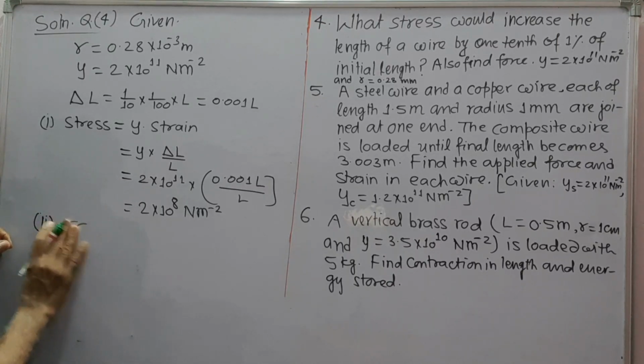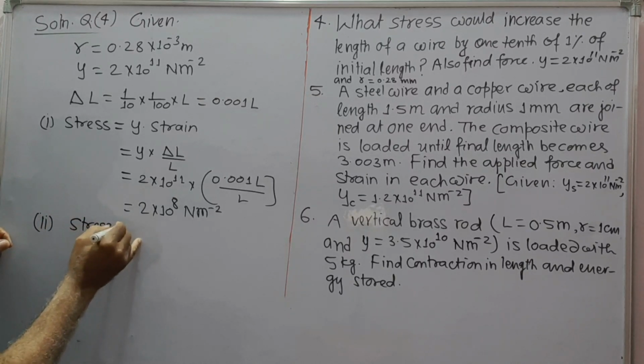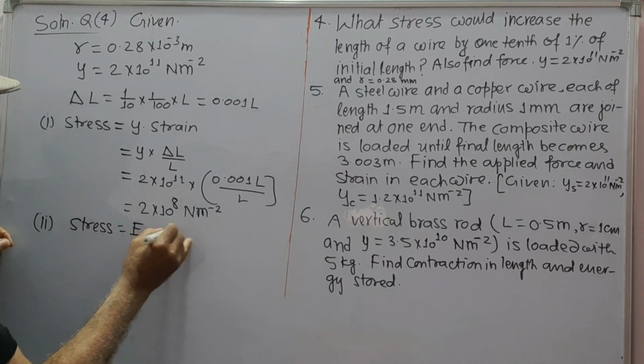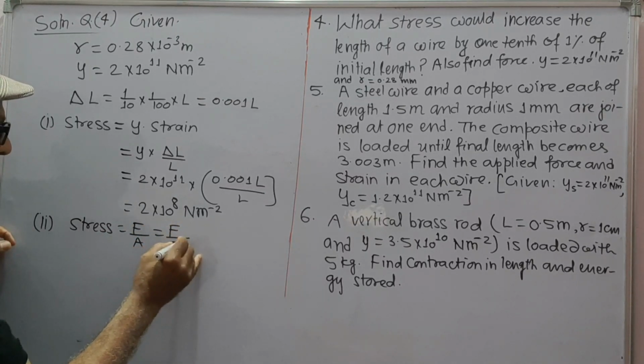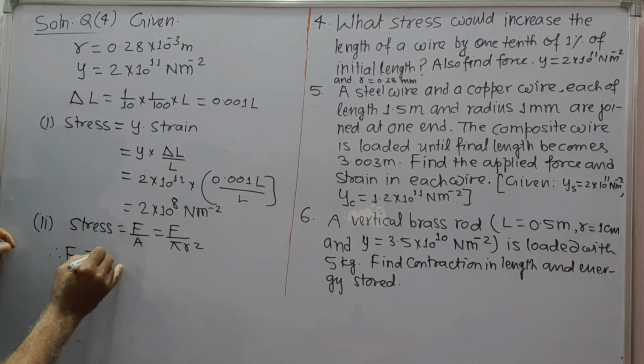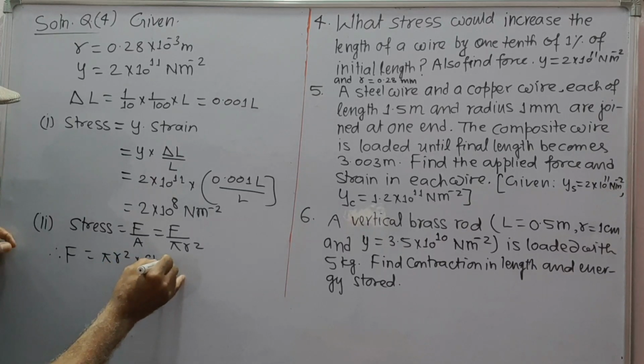Second part, force. Stress is equal to force upon area, force upon pi r square. Therefore, F will be equal to pi r square into stress.